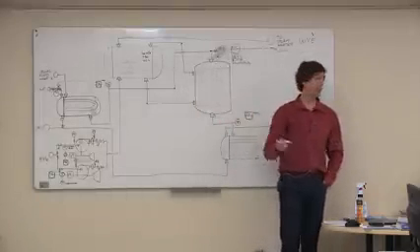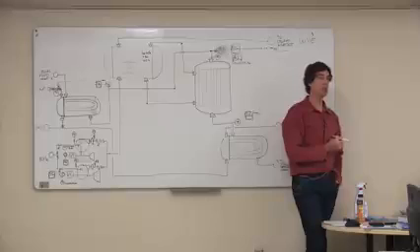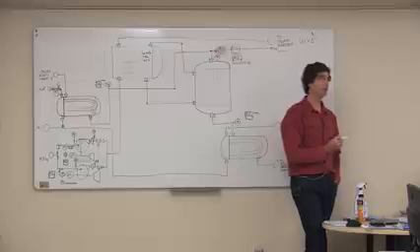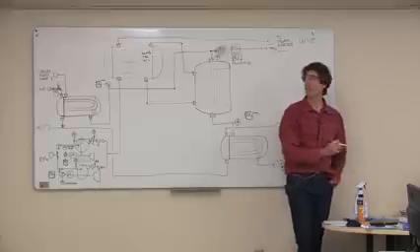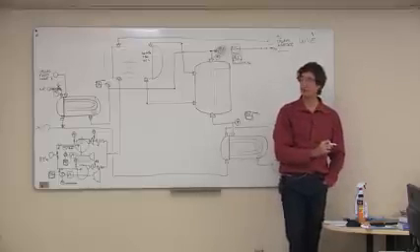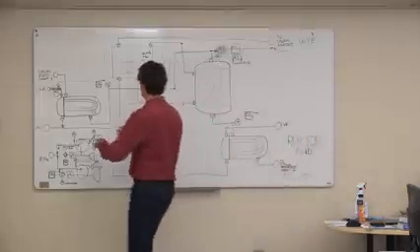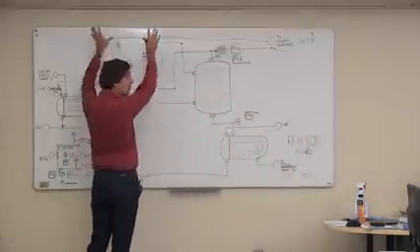Because that's what dictates the heat transfer in a heat exchanger. Not the flow rate. Not directly the flow rate anyway. If we add more boiler feed water, we're just going to overflow the steam drum.